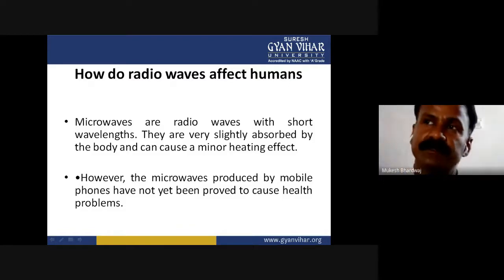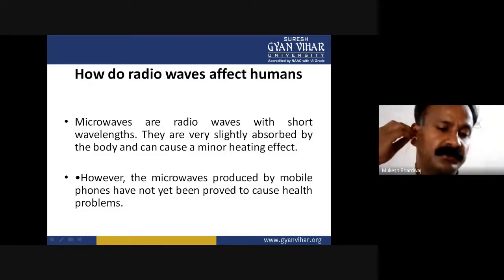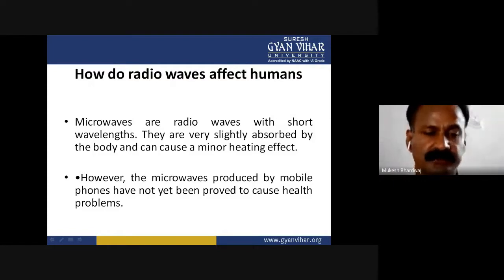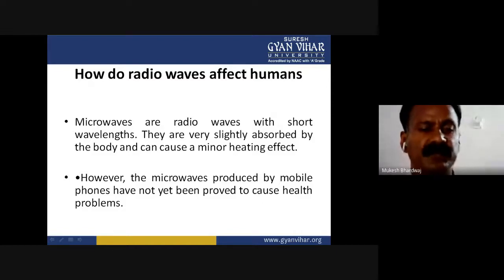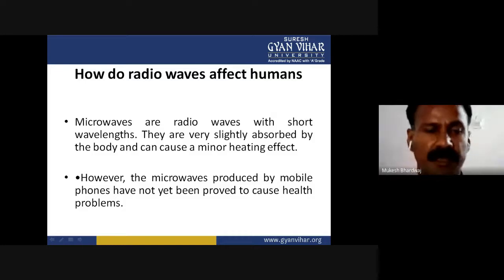Doppler motion sensors use the Doppler effect, that is, the change of frequency of a wave when reflected by a moving object. Doppler motion sensors are used in vehicle speed monitors for traffic control and intrusion alarms. The quantities required to be measured in microwave circuits are frequency, power, and impedance. Microwave frequency measurement is done by slotted line, resonant cavities, and transfer oscillators.